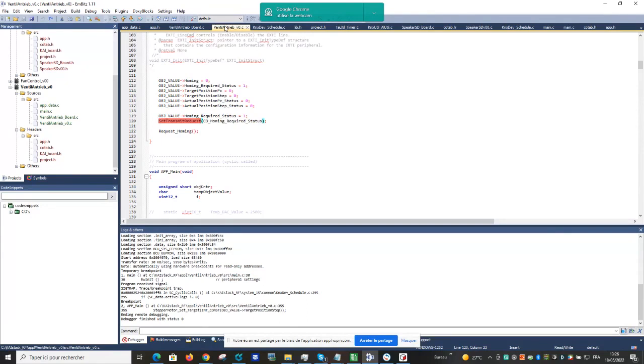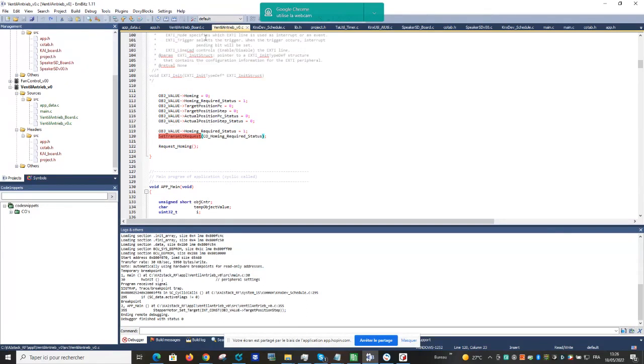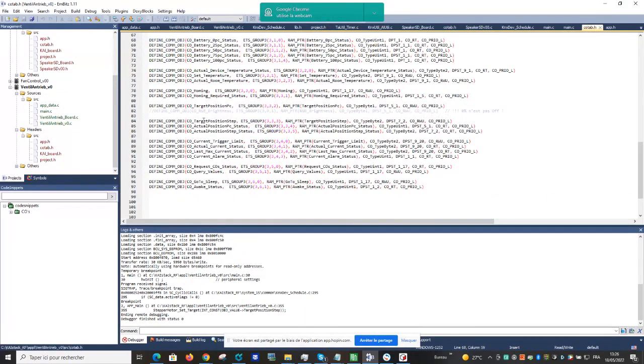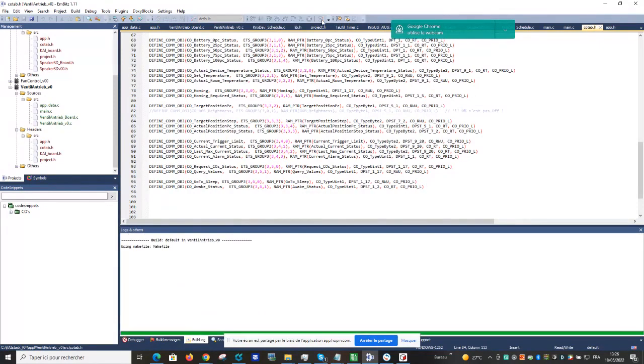Just for example, let's make a little test. You saw we have an object. You see, for example, here we have a communication object, address 333, and it's of data point type 7.2. Now what we do here is we can compile the project and connect it to our prototype. This is going with the items I showed just before.